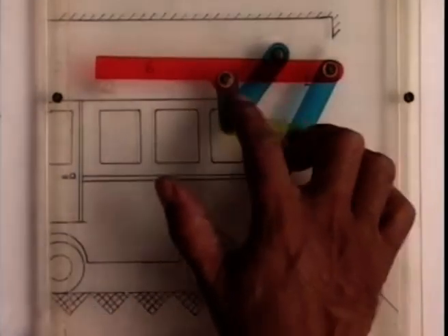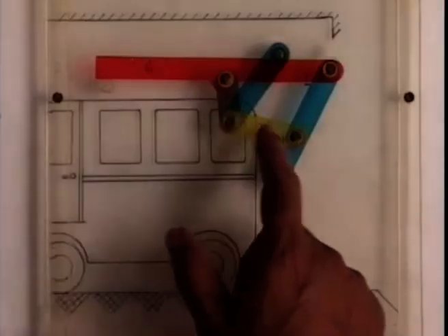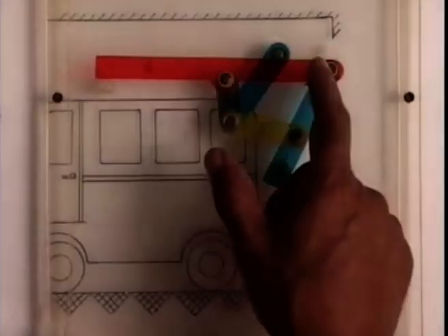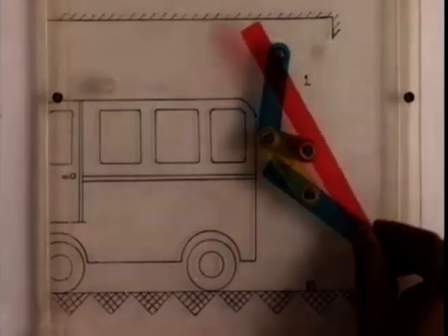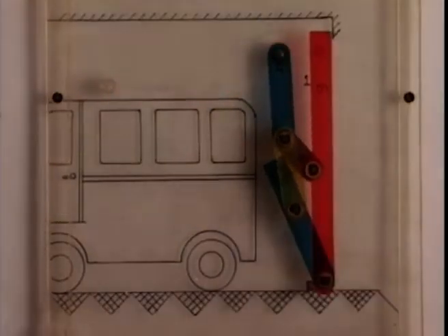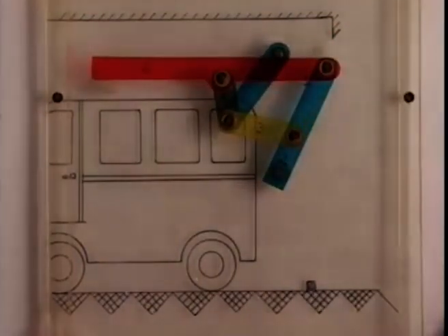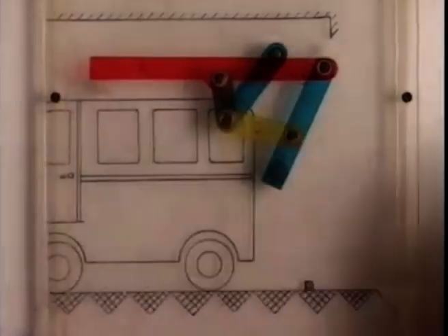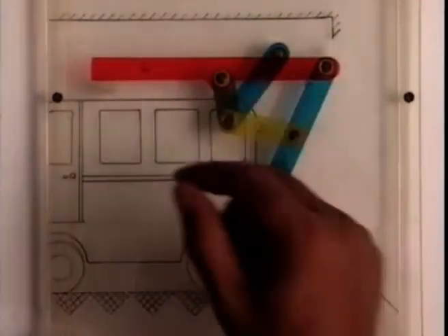These mechanisms are mounted on the sidewalls, so there is no obstruction with the car. It is only the door board which moves inside the garage and closes the garage or opens it. The thing to note is that there is no prismatic pair. The entire mechanism consists of only revolute pairs.